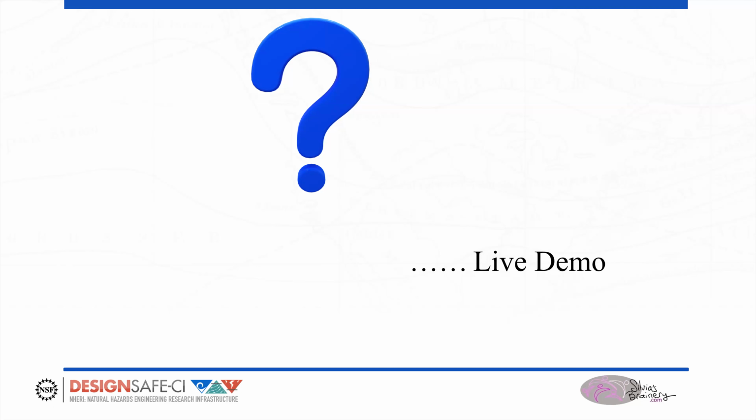And so now shrink that into something that's manageable. Maybe my computer can only run one such model at a time, or it depends on how much memory I have in my computer to be able to run 7 analyses. If I run 14 analyses, I'm doubling the requirements on my memory. So don't use all 56 processors if you have a relatively large model.